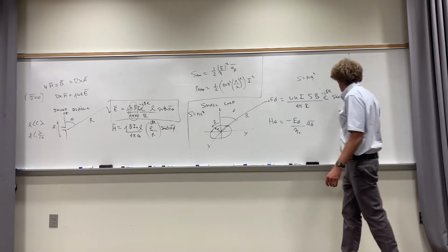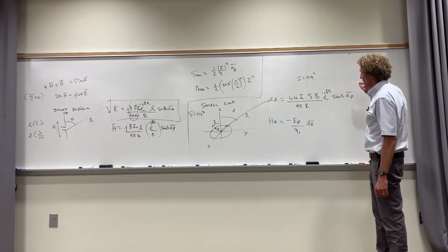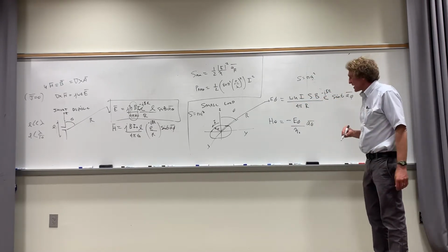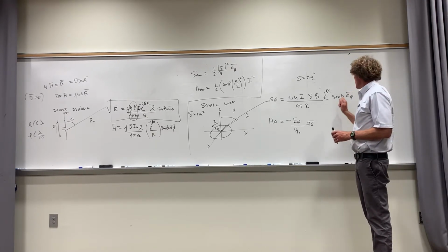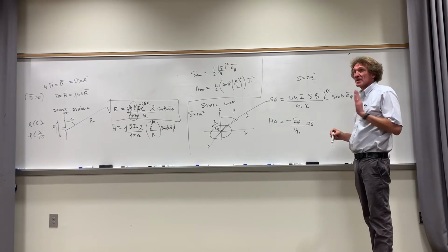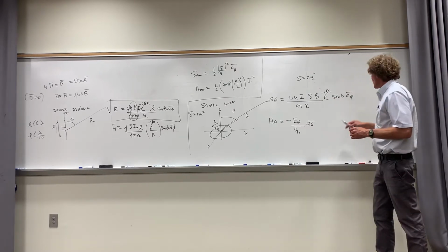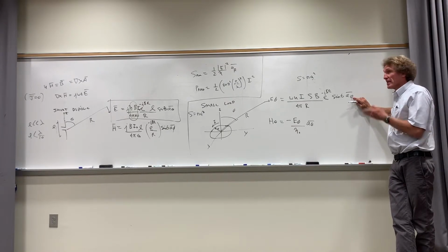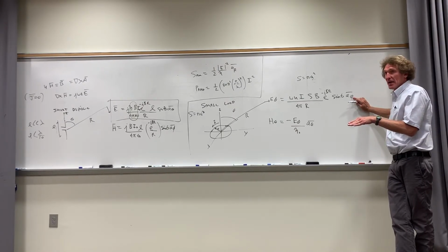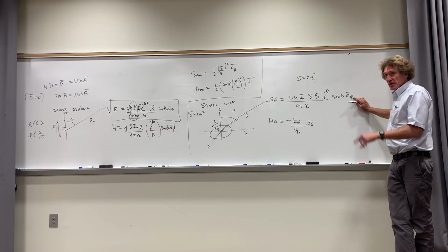So you take the scalar value, divide it by eta, and put a minus sign, and you get the H field. The reason that H field has a negative is because when you take this cross this, it has to have a radial component. So if I take A phi and cross it into A theta, I would get minus AR. That's the reason there's a minus sign there.